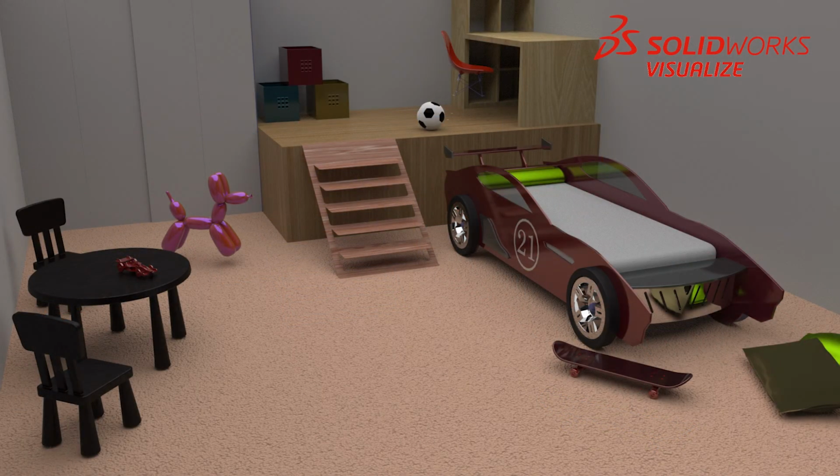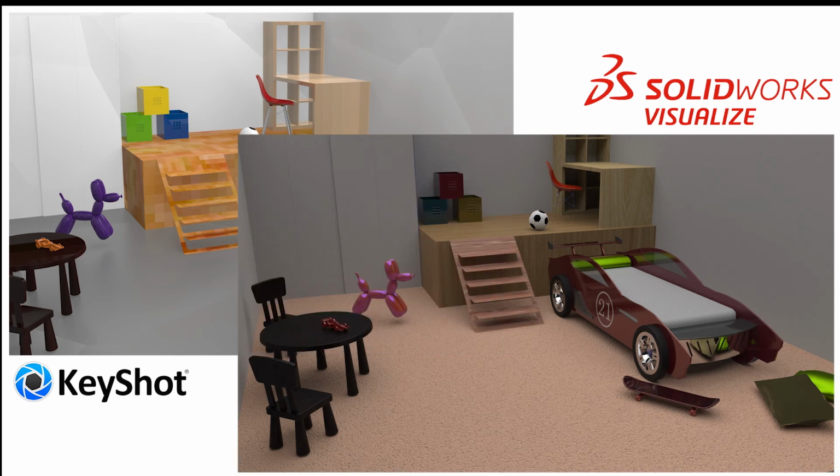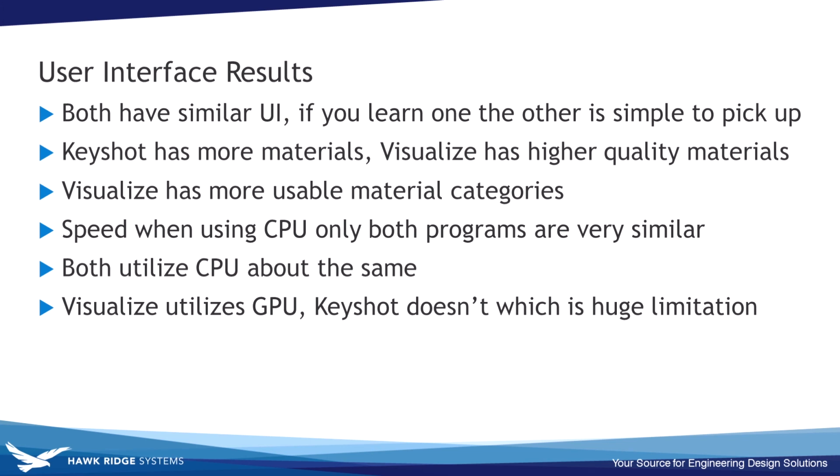But that doesn't mean that Keyshot can't do better than this. I used pretty much out-of-the-box settings in both applications, so this is what you can expect to produce without going back in and fine-tweaking all the material, lighting, and camera settings. And really, this is because the ability to utilize both the graphics card and the processor is hands down the way to go. It reduces rendering times by at least half, and that can be greatly increased with some of these high-end graphics cards.